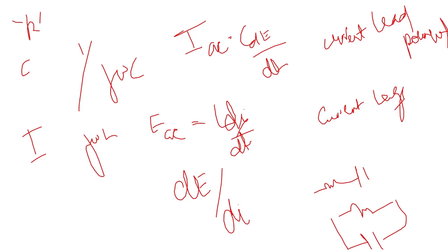Okay, so all this you saw in the next week after that. There also omega tends to 0, omega tends to infinity, you will solve, then the step frequency. From that you will be asked to find the real part, imaginary part, modulus you can take, phase will be tan inverse of imaginary by real. So all those you know. Then you saw how you will represent it. It can be by Nyquist plot or it can be by Bode plot.